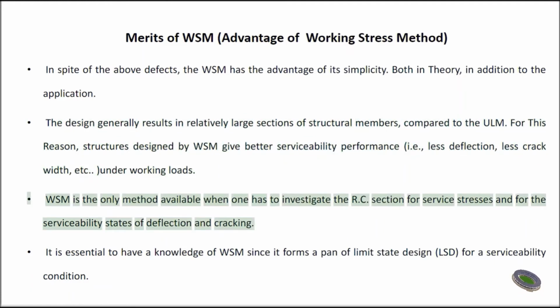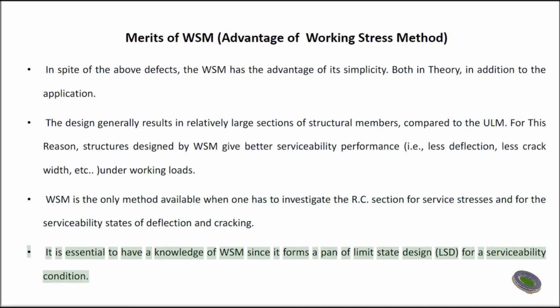WSM is the only method available when one has to investigate the RC section for service stresses and for the serviceability states of deflection and cracking. It is essential to have a knowledge of WSM since it forms a part of limit state design, LSD, for a serviceability condition.